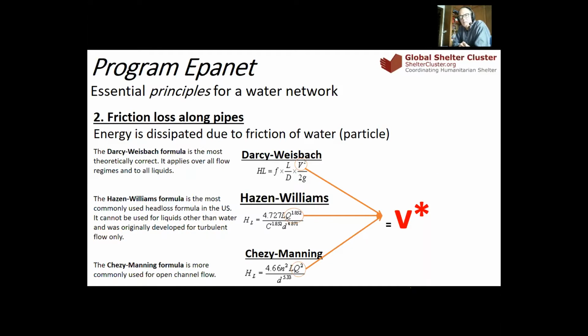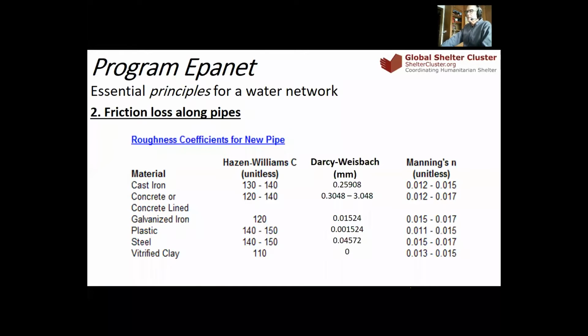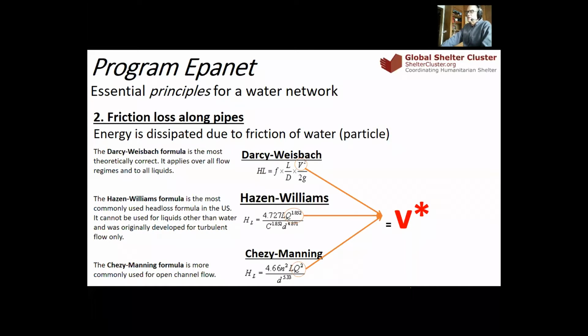That's why velocity in the pipe is an essential parameter that you should consider when you develop a network. And the velocity in a pipe should not exceed 2 meters per second unless you need to dissipate energy. If you have too much energy, if your tank is too high, for example, then it might be a good idea to have a very high velocity in the pipe in order to dissipate energy along the pipe. Depending on which formula you choose, you have also to...